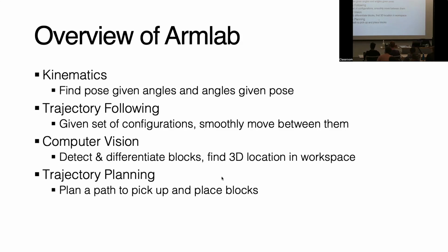Then we will be doing a lot of computer vision. We will be using the RGB image and the depth image from our camera, and then using OpenCV to figure out what blocks we're looking at, to differentiate between the red, blue, and green blocks, and between the large and small blocks, and to figure out, if I have a stack of blocks, where the top block in the stack is. So I can pick it up and take it off the stack, or pick up a block and put it on the stack. That's all computer vision.